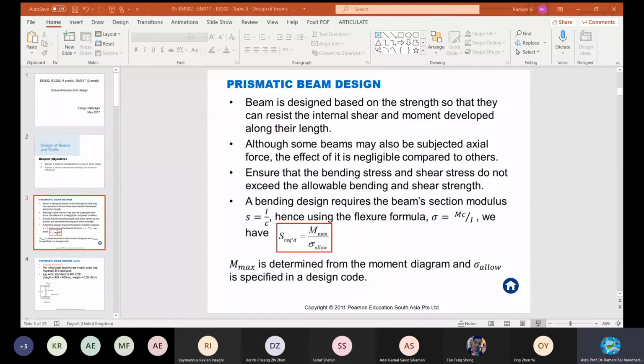The AISC, American Institute of Steel Construction, has standards. W460 times 68 is shown like this. The height is 459, end to end, approximately 460, right? The missing 1 mm will be due to the material, because sometimes they cannot get a very clear cut dimension. So around this value will be designed, and the weight is equivalent to 0.68 kilonewton per meter. When I say 0.68 kilonewton per meter, you are able to imagine the value.